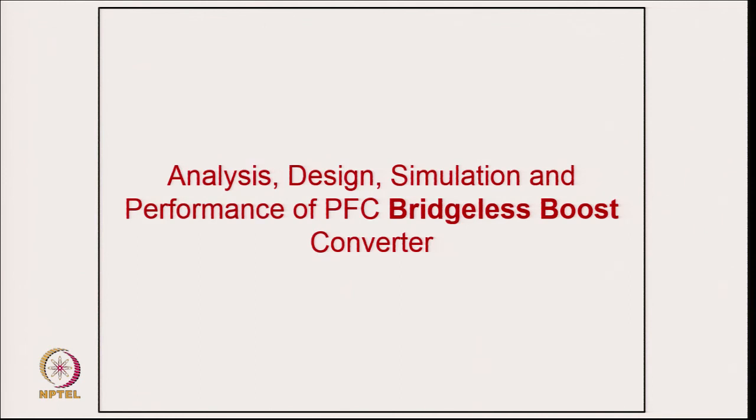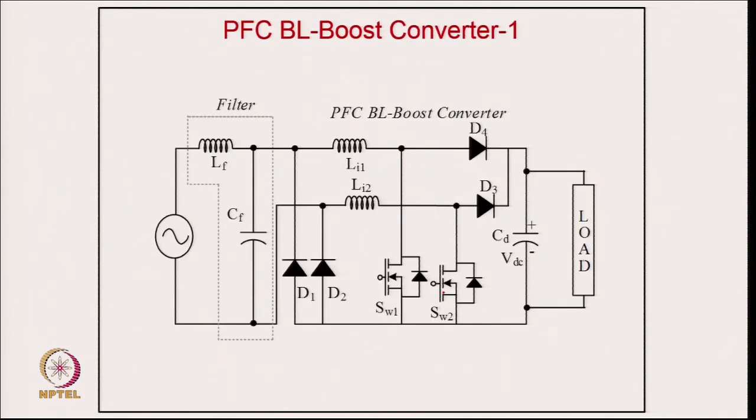So now coming to the analysis, design and simulation of performance of PFC power factor correction bridgeless boost converter, and this is typically the bridgeless boost converter. You can clearly see here we have eliminated the bridge. In one positive half cycle, one boost converter works, and in the negative half cycle another converter works. That is what we call power factor correction bridgeless boost converter configuration 1.